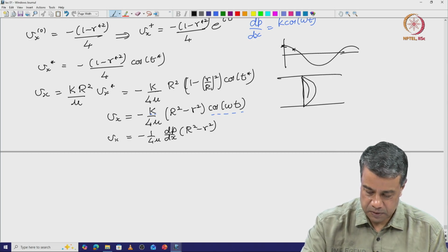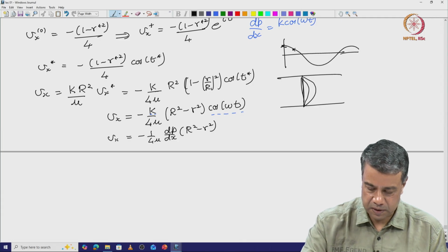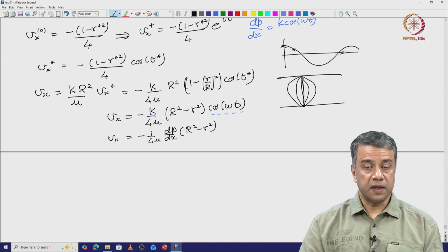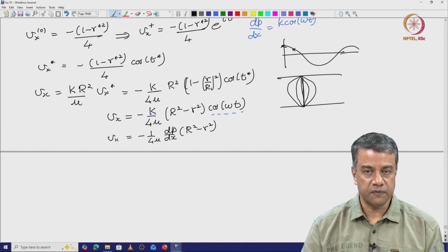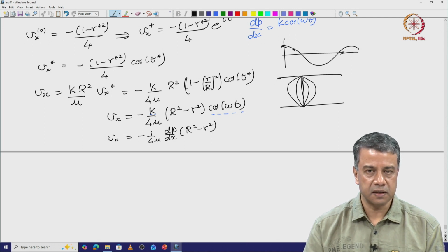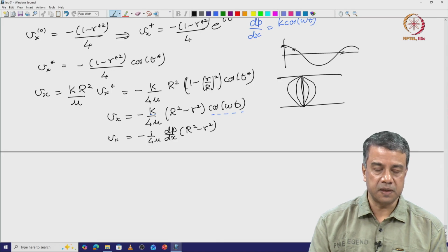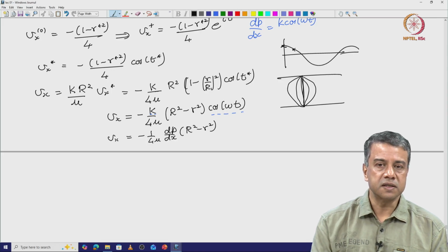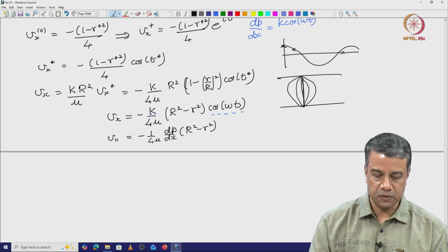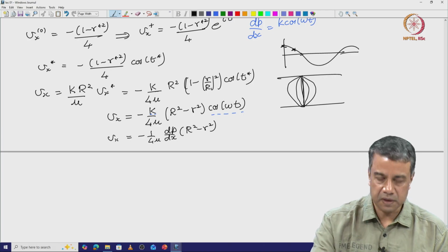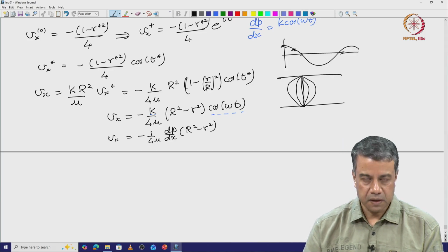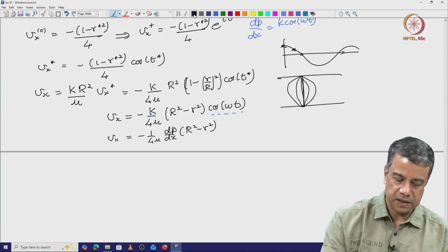At this point it is lower and it passes through 0 here and it goes the other way as well. You are getting the same solution as you would have got for a parabolic flow for a steady pressure gradient. For this particular oscillatory pressure gradient, the solution is the same as that for a steady pressure gradient with that instantaneous value of the pressure gradient at that point in the cycle. Now, why is that? Let us look physically at what is happening.